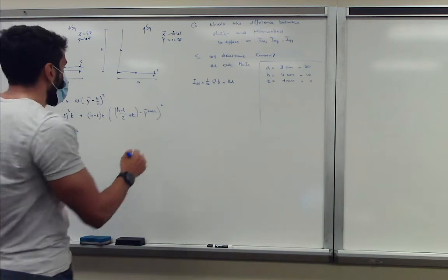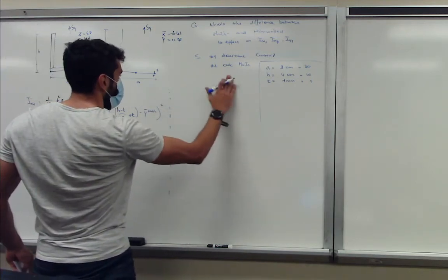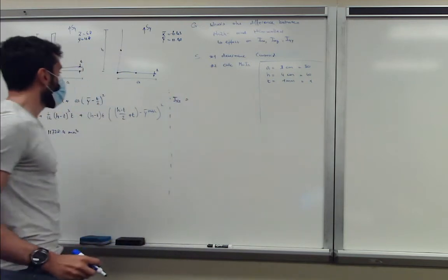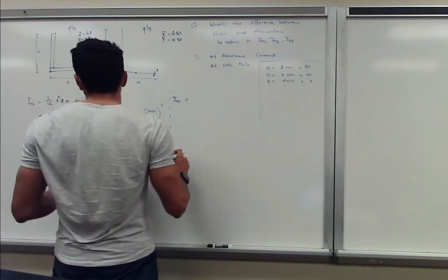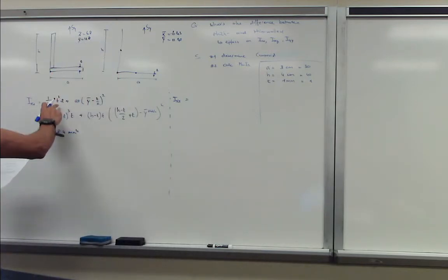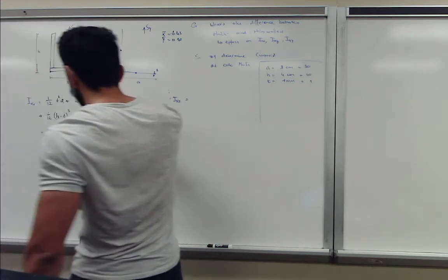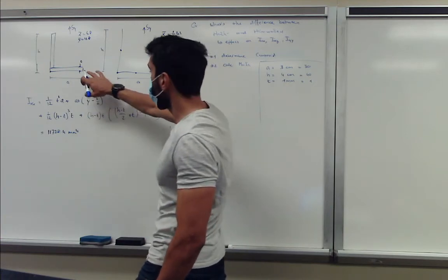And then we can do the same thing for the thin wall Ixx. If you always do the thick wall first, you can basically see which terms disappear under the thin wall assumption. In this case, the 1/12 t cubed term would disappear, so you only have to deal with the Steiner term, and of course you ignore the local thickness.